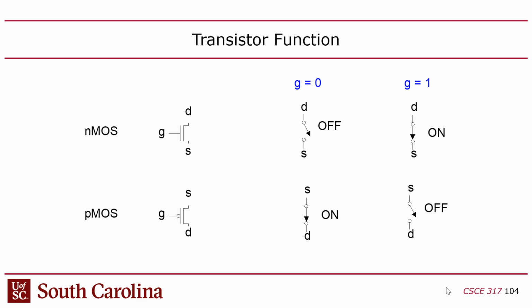Both transistors have 3 terminals: a gate, a source, and a drain. The gate controls whether the source and drain are connected electrically or not. Technically they're always connected, but if you turn off the transistor, it raises the impedance between the source and drain to the mega ohm scale. When the transistor's on, it reduces the impedance between the source and drain to something like less than an ohm. So it's really making the resistance super high or super low.